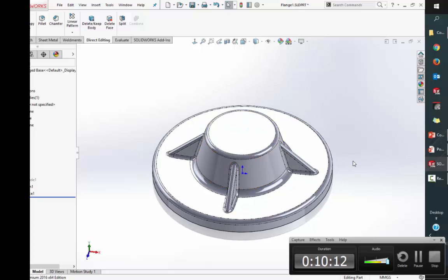All right, so does this look like a little bit better casting? Sure, I'm going to go ahead and say this might be okay. Now, what I did here was I was in the forging at this point, and I said get rid of the holes, and then I said, you know what, I've got to get rid of this hole as well. Now, when I got rid of the hole, you can see at the bottom I had to add a new feature. This delete face is a feature.